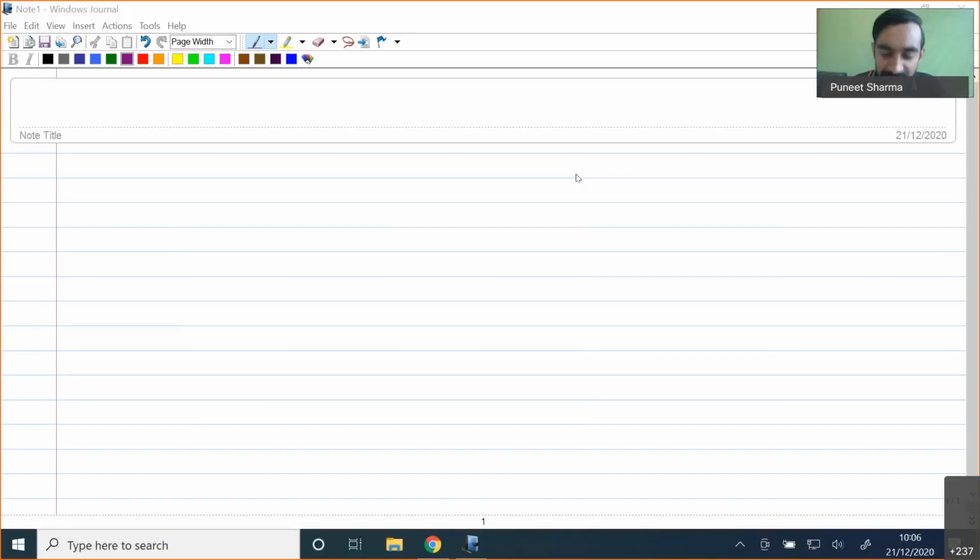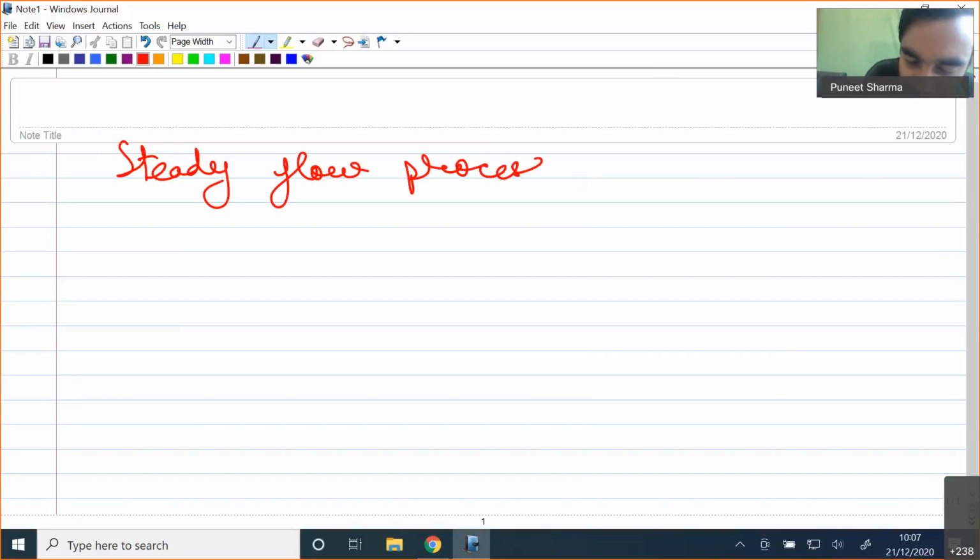Course Engineering Thermodynamics. In our previous lecture, we started our discussion on the first law of thermodynamics for open systems. In terms of open systems, we have seen the mass conservation and energy conservation equations. Apart from that, I have also explained a special type of process, which is known as the steady flow process. In a steady flow process, the change of property of the control volume or system with time is equal to 0.